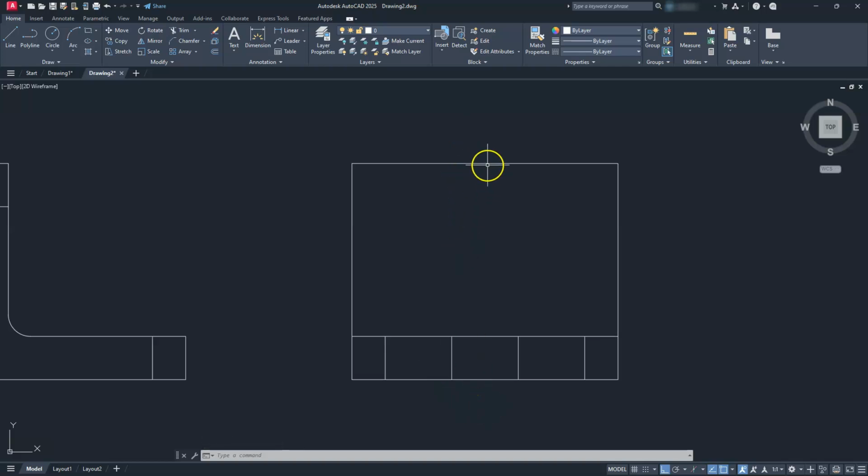Let's go ahead and put our circle that's located here. So I'll go to circle, center radius. And we can also use an arc if you're comfortable using arcs. And maybe this time I will show you using an arc. Typically what I would do, and I'll show you this and then I'll come back and get rid of it, but I'll start with a circle center radius. I'll click at this midpoint. And then I'll go ahead and type in the radius of my circle, which is going to be 30. And then I'll just trim this, right? So we can use the trim command and go ahead and knock out these. Nothing wrong with doing it this way, right? But I'm going to undo back.